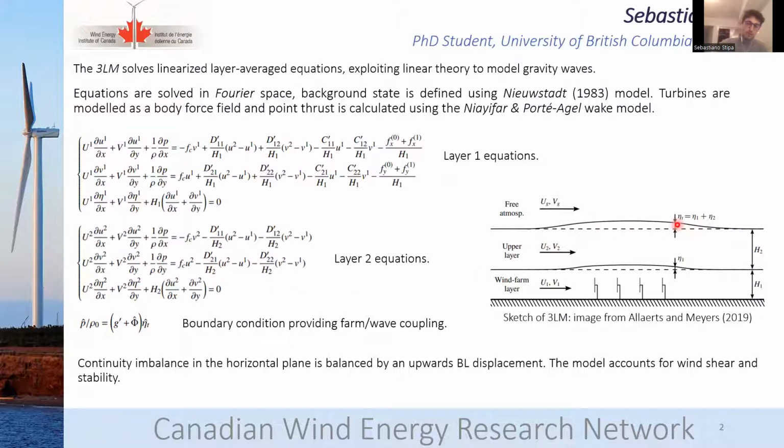You can relate it to the pressure perturbation. The assumption that is made is that the pressure perturbation propagates vertically inside the boundary layer and does not vary with the height. This is a hypothesis which is usually made in boundary layers because the pressure is not perturbed up to second order, basically.